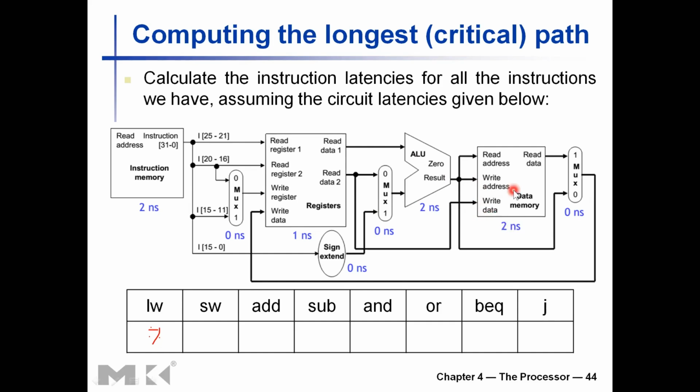When the next positive clock edge happens, it will take about 2 nanoseconds to write to the data memory also. If the next instruction is a load instruction, it will take 1, 2, 3, 5 nanoseconds for the read to start from the data memory. So taking 2 nanoseconds to write the previous value is all right. It doesn't matter. It won't corrupt our values. So for the store word instruction, 5 nanoseconds are required to complete the operations.